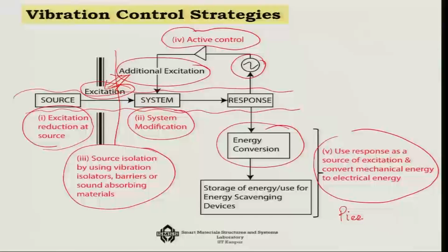Piezoelectric materials precisely do that. I will show you later on that piezoelectric materials can convert vibration into electrical energy, and then you can keep a capacitor and a battery system, so that you can charge batteries out of it. So, that is my fifth strategy of vibration control.